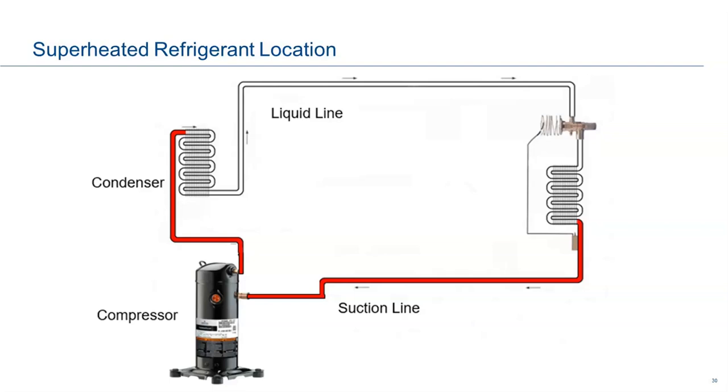But we want to take a superheat reading there because we want to confirm that we only have vapor going into our vapor pump. Even if it's only 5 degrees or 6 degrees or 10 degrees, we know we have something, okay? All right? But we want to prove that. I'm also going to ask you a little known fact here, or maybe a lot of you know this: I want you to add this to your tool belt starting tomorrow.